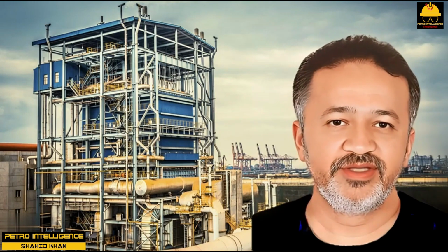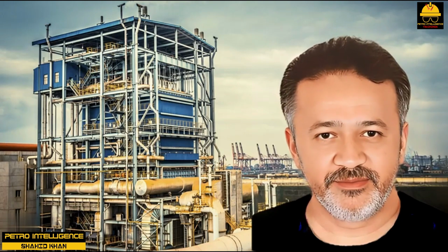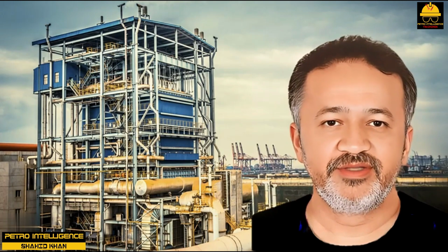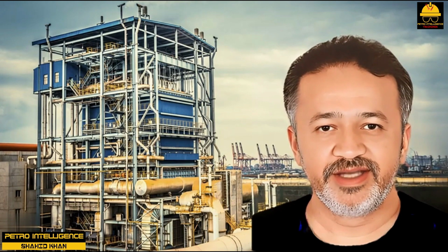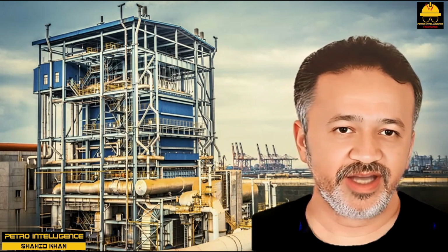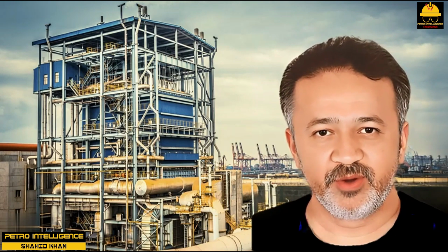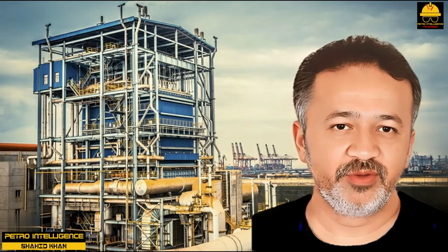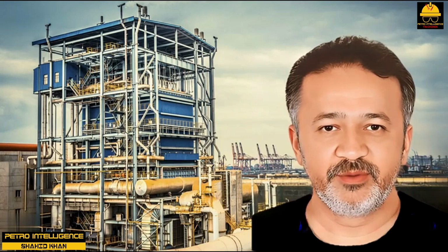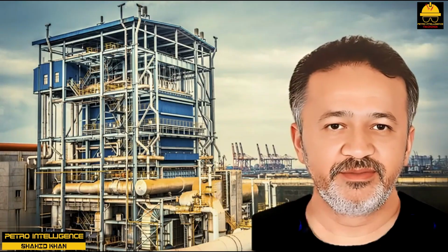The overall performance of these exchangers did not improve all that much, according to our client, after the new twisted tube bundles were installed. However, they also converted the exchangers from 4 to 2 tube side passes, and this decreased the tube side velocity by half. Presumably, the reduced tube side velocity offset the benefits of the twisted tube design. Converting back to 4 passes is difficult, because the tube ODs are so tightly packed with twisted tubes, and there is very little space to accommodate additional new pass partition baffles.